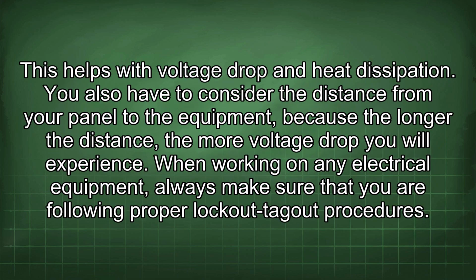This helps with voltage drop and heat dissipation. You also have to consider the distance from your panel to the equipment, because the longer the distance, the more voltage drop you will experience.